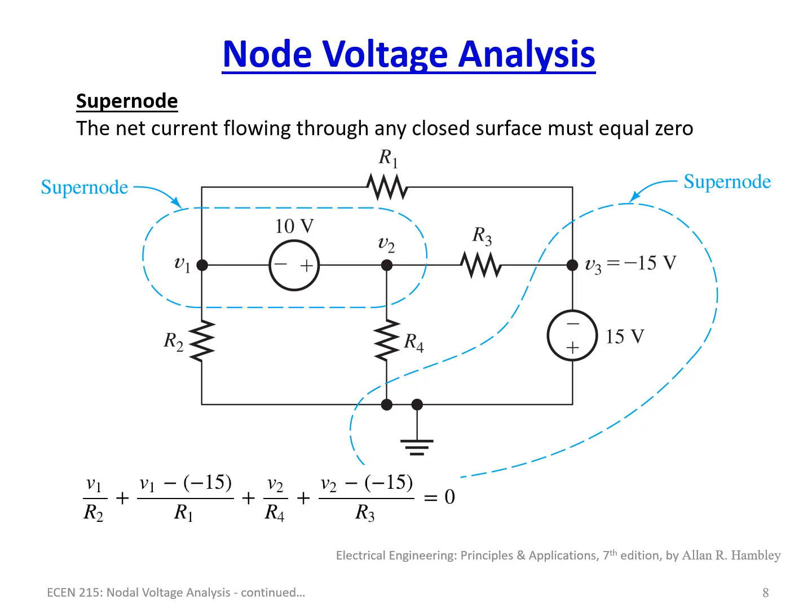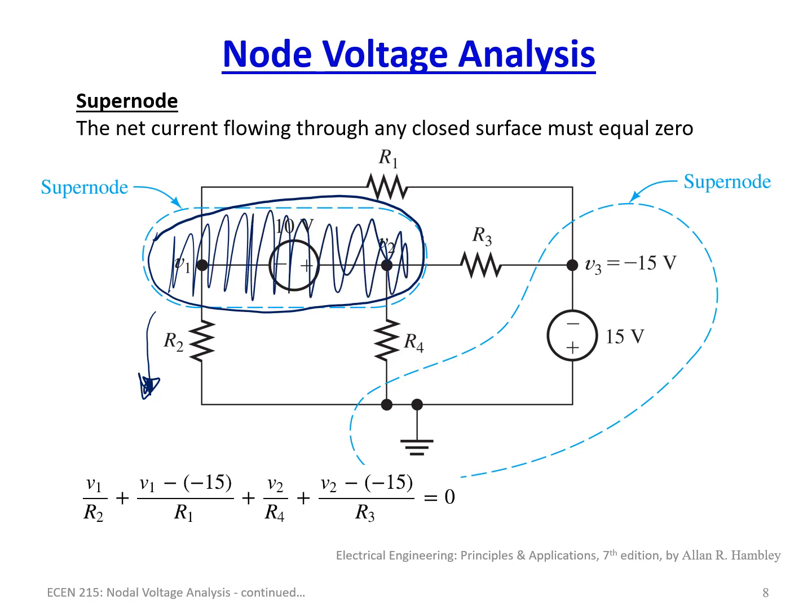Which, if you wrote the equation for this particular problem, works out like this. So with V1, you still keep the same nodes. That's what makes this a little convoluted to think about. It's basically combining a couple of equations for you. So I'll try to step through this slowly here. We have V1 over R2. So again, if we draw our circle here, and we're just looking at what's flowing out, we first get this current here, V1 over R2. That's this current here. In fact, I'm just going to hash this right here, so let me make it a little more obvious.